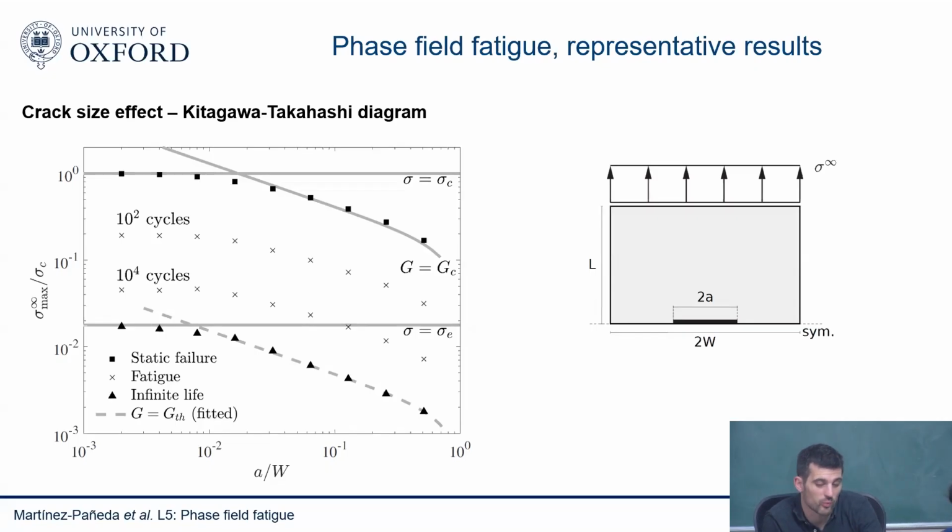It depends, because when you do fatigue crack growth, you are damaging what is ahead of your crack. It might not be a bad approximation, but you are cycling and you're already damaging this zone here. So it will be slightly different from the case where you start with a crack like this and this is undamaged. It could be a bit of an effect, maybe not a strong effect. You're right, it could be interesting to test that.